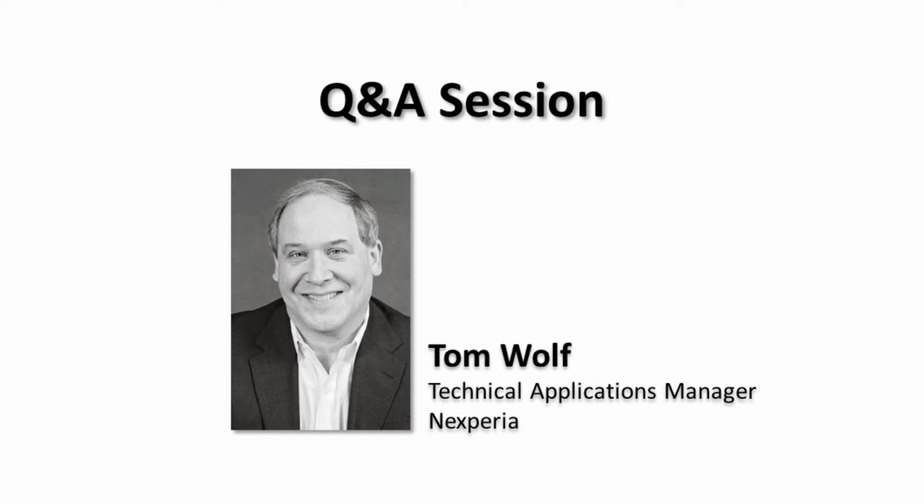Okay. Will Foster models run on the standard SPICE as well as the LTSpice tools? Yes, correct. The Foster models are RC models, and so they will run on SPICE, which is the licensed version you have to buy. It's a little more elaborate, but it works on that. Of course, LTSpice is the free version you can download. It works equally well on that. The same model works on either tool. It's just, is it the commercial version or the free public version? That's all.